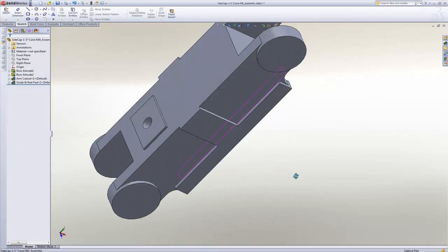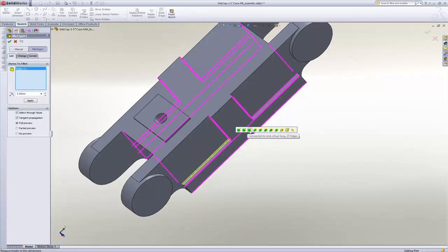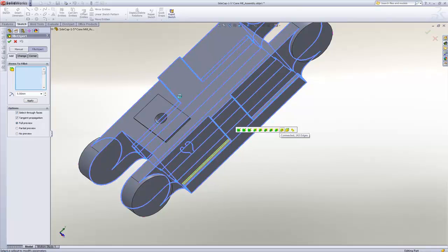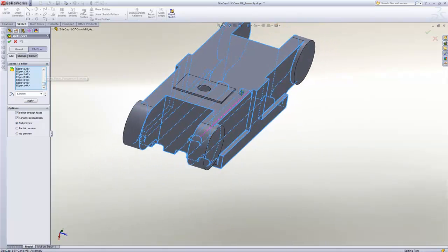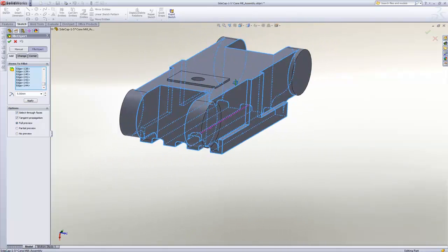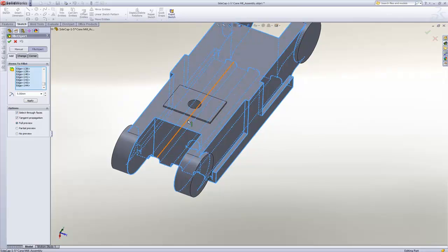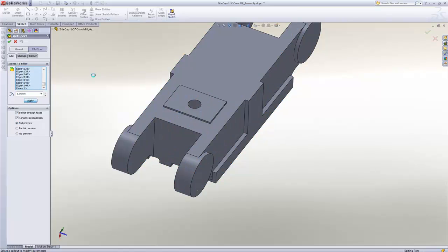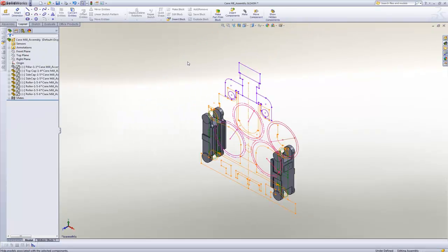To round the sharp edges, we'll take help of SolidWorks Fillet Expert, which would help us in selecting large number of edges in one go. Now in this case, we have picked more than 140 edges and we'll get filleting done in all those edges with a single mouse button click.